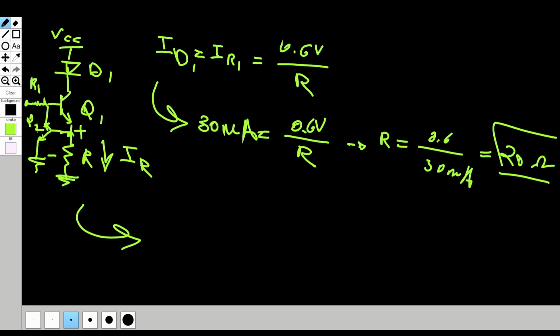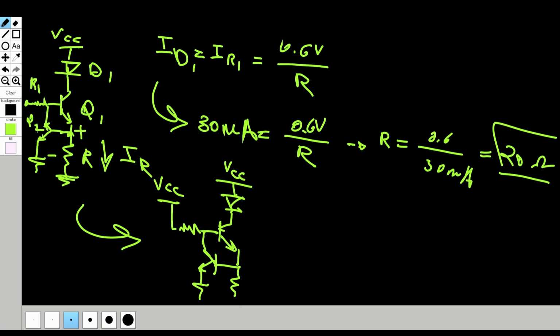So basically all you need to do is, instead of having the node at the base of Q1 connected to the MCU, you're just having it directly connected to the VCC, right? So this could be just connected to VCC, like this, and then this is just connected directly to VCC. There you go. So now you have it connected directly to VCC. So it just means that this will always be on.